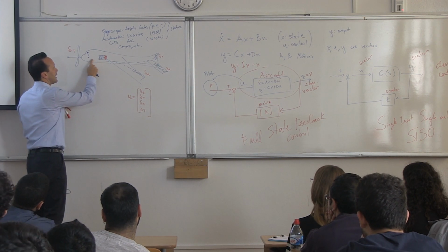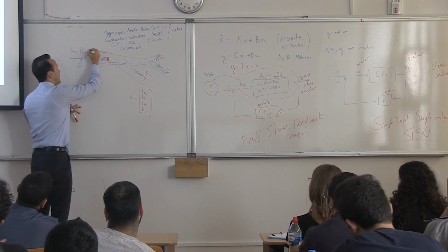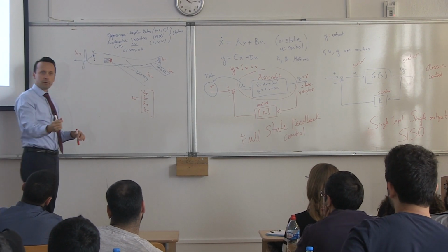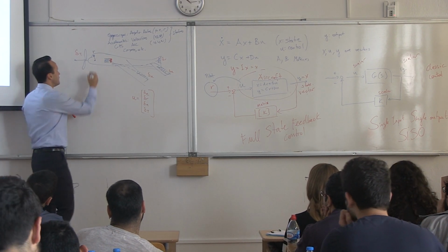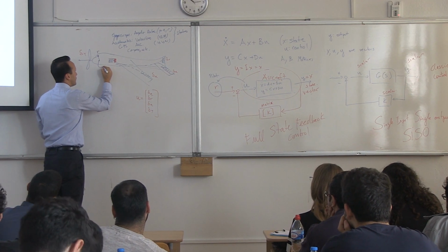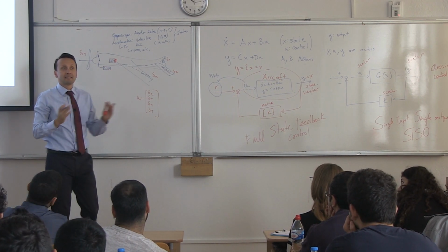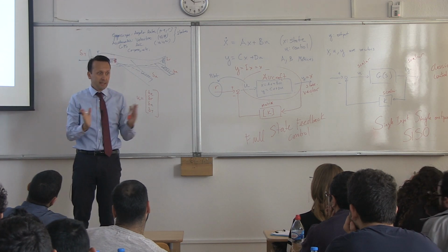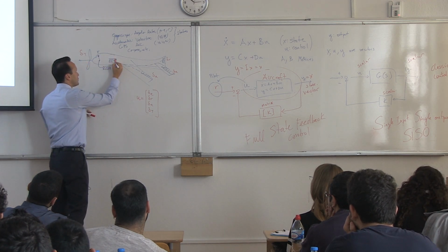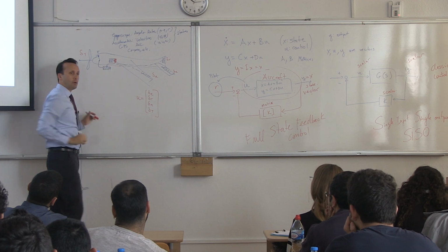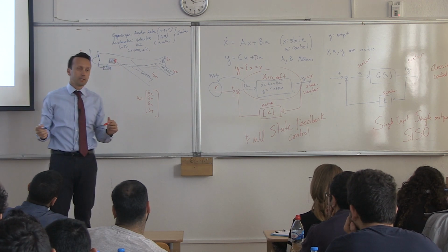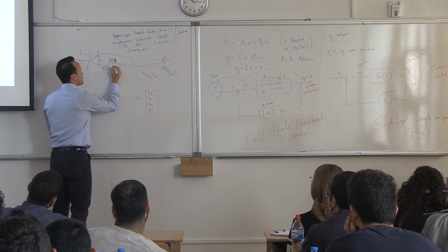So we cut this line. We say, pilot, this is R now, your pilot stick position. We take this position. We put another actuator over here. Actuator meaning a servo, a hydraulic, something like that. Connect that control system to that actuator and send that to the controls.